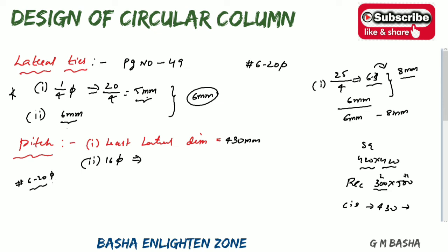But in rectangular or circular columns, if we provide 8 bars, there is a chance of providing 4 bars of 20 dia and 4 bars of 16 dia. At that time you have to choose the smaller diameter, 16. Here there is only one diameter, 20 mm. I will explain in further classes if you get such conditions with different dia bars.